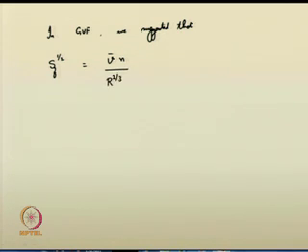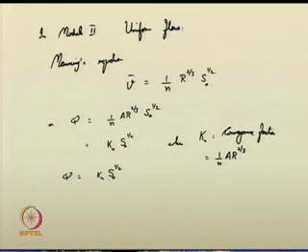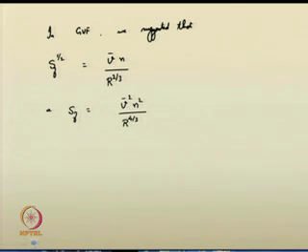R to the power of 2 by 3, or S f is equal to V squared n squared by R to the power of 4 by 3. So, now you have expressions for S f, and you have expressions for S naught also here. S naught you can easily think now in the following terms. Therefore, S naught is equal to Q squared by K n squared, right. So, that thing you can think in those terms now.